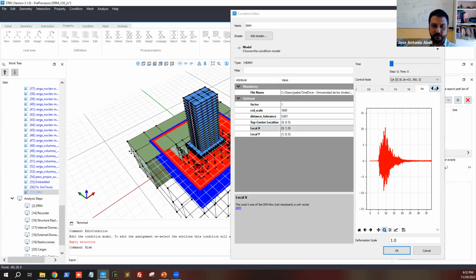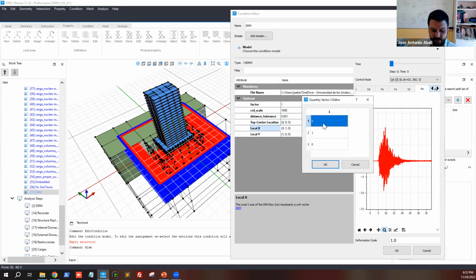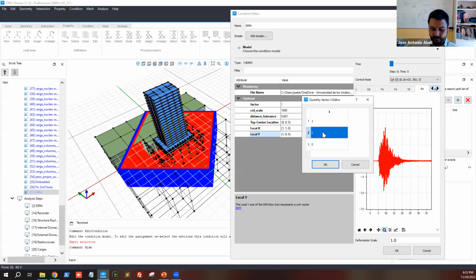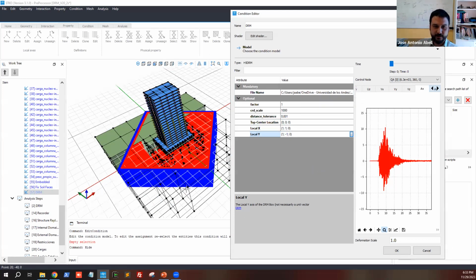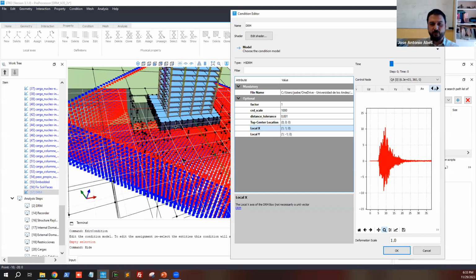Another thing over here is that you can rotate the box with these local transformations. So I could say something like, I don't know, I'm going to mess this up. It's going to look horrible, but bear with me a little bit. Something like this, maybe. So you can rotate the box and apply some transformation, and these are just the unit vectors of the local x-axis and y-axis, and the z-axis is computed automatically as a cross product of these two vectors. So it gives you a way to rotate your box around.